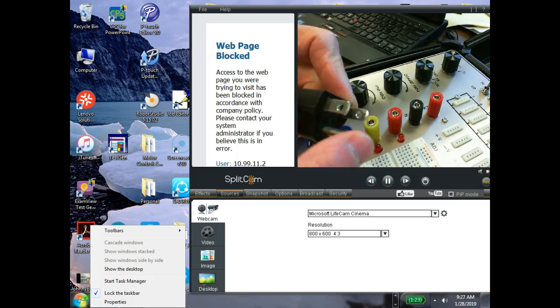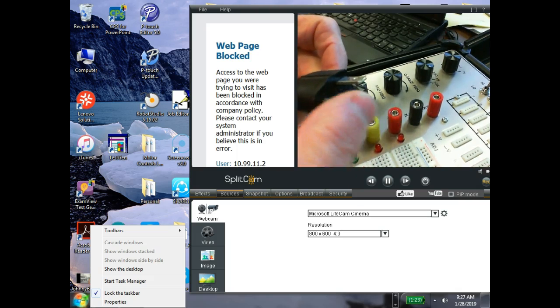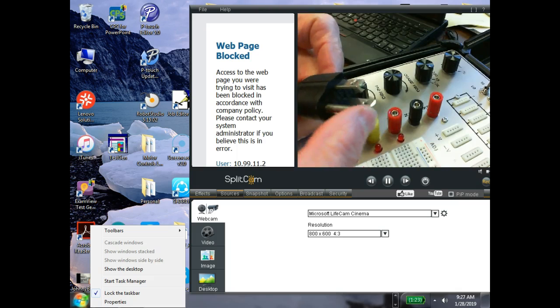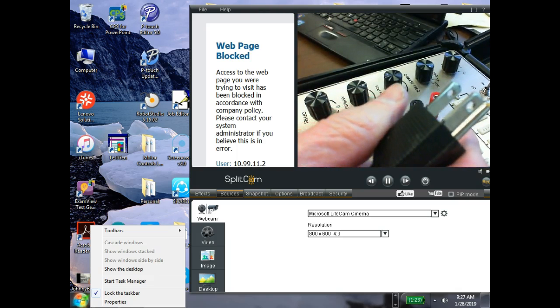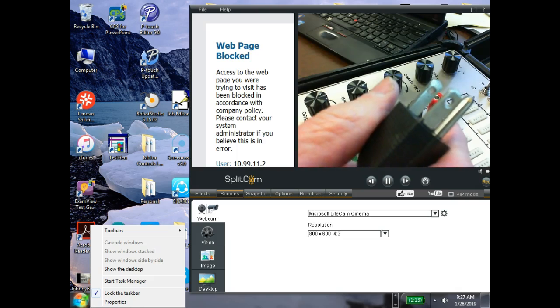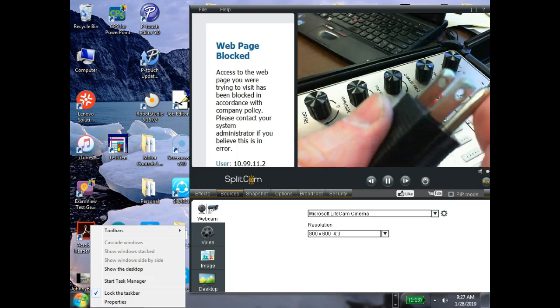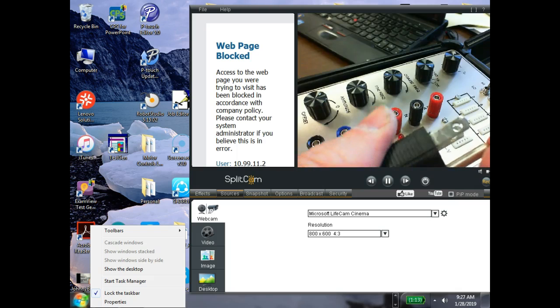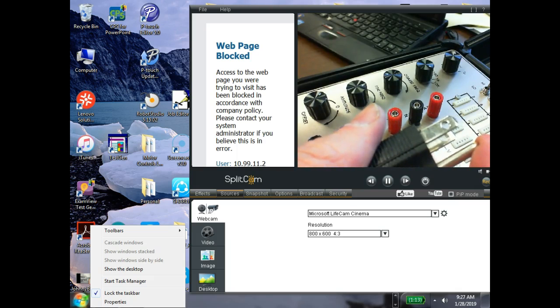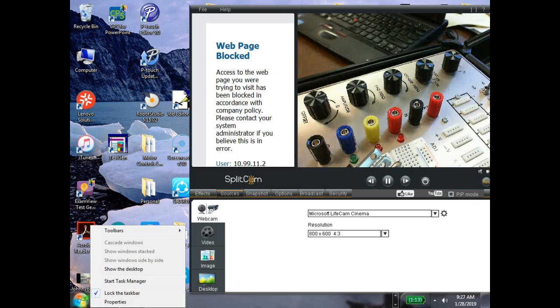Well, this is ground. This is ground on this guy. This is AC. So ground is somewhere there is a nice big copper rod driven into the earth, and this wire right here is connected. That is ground. Right? You understand? A common is just, so does my meter, does this guy here have a ground? No, it's got a common. So a common is just that reference conductor that everybody brings it back to the other side of the power supply. That's a common. So we have a common, right? You understand? And we have ground.